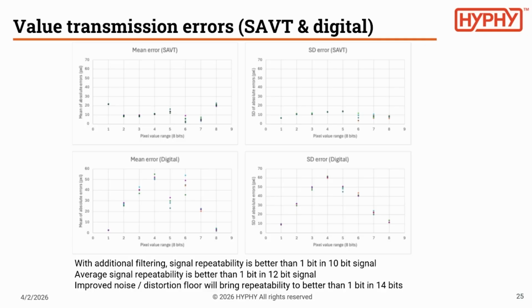For this, as I said, without FIR filtering, you can see that the results for any bit value are approximately 10 bit values away, so 10 out of 1,000, and the standard deviation is about the same, so that looks like good transmission. And here is the digital transmission, where you see 5 times, 6 times the error range.